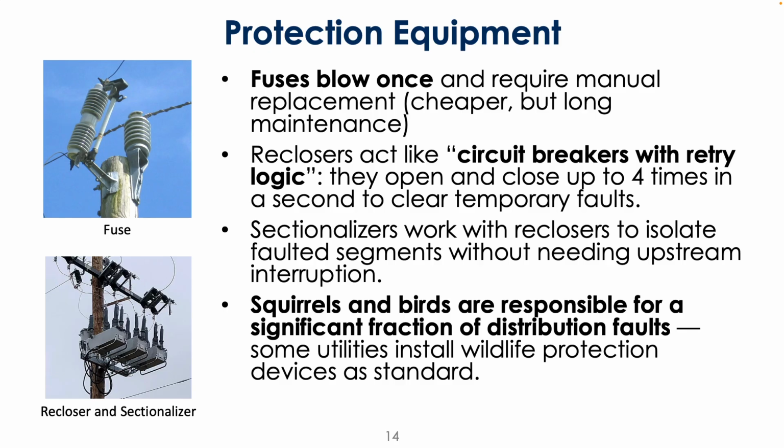It's more than its rated capacity, and you melt the paper insulation between the coils. You blow the transformer, and now the utility has to come out and replace it. You've got a blackout for whatever customers are served electricity from that particular transformer.